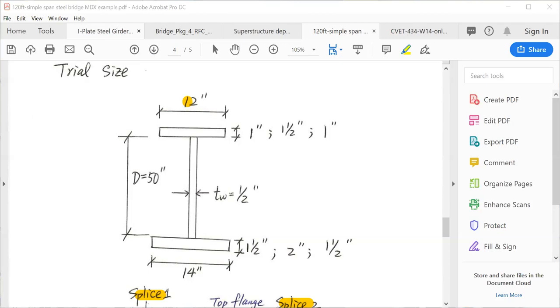And girder system design is where you want the program to design the girder. It sounds pretty good, giving you some dimensions of the top and bottom flange and web size, but in real-world design, we don't use this option because the software is not that smart, and usually the design is super messy and generates unnecessary work.